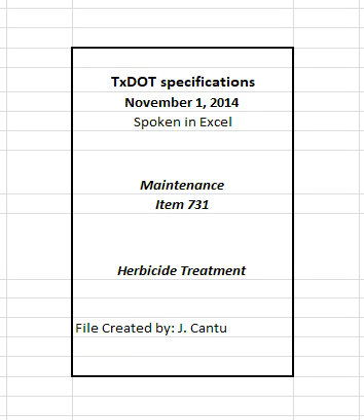6.1 Broadcast application. Furnish self-propelled equipment, tractor-mounted or pulled spray rigs with a low center of gravity that allows a safe traverse on a maximum 3:1 slope. Provide equipment capable of making uniform broadcast applications calibrated at a rate between 20 and 40 gallons per acre, GPA.